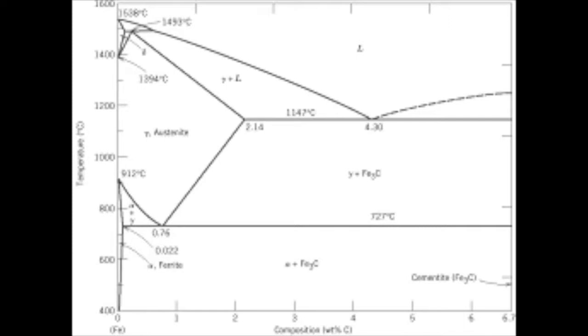This steel was chosen because it has a relatively low carbon content, which leads to a high toughness, which is important for this specific application. As previously mentioned in the manufacturing portion of this presentation, the bar is then cold rolled or machined down to the necessary diameter. Either way, this leads to internal stresses within the material. After the bar is cut and bent into shape, more internal stresses are induced.